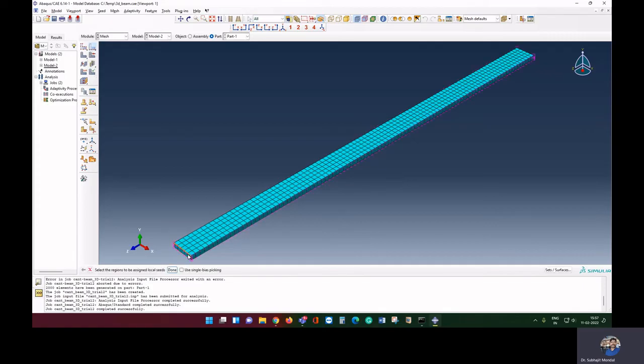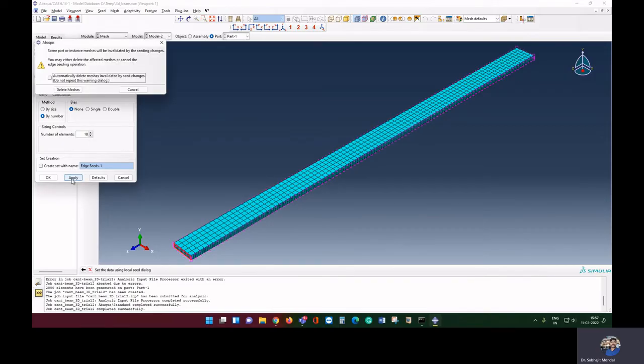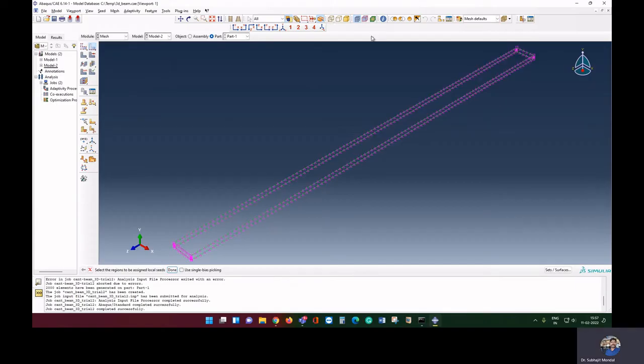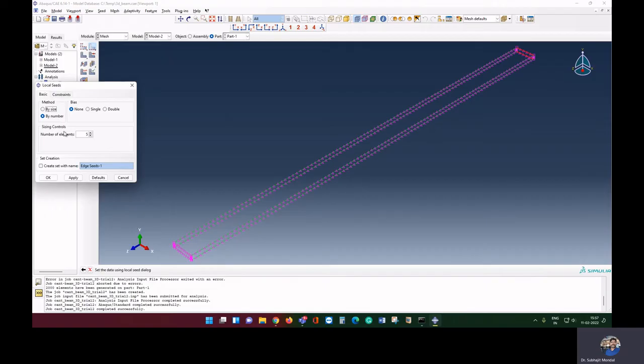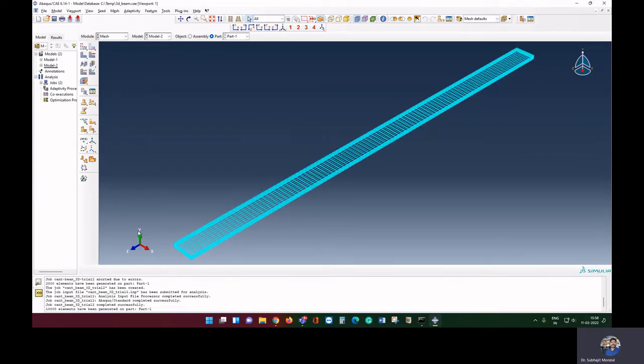So now we'll do one thing. We'll increase the mesh size along this width. Now here my number, I will try to make it as 20. No, sorry, 10. I'll make it as 10. This side also I'll use as 10. Here also I'll use 10. So I will make the number 10. Okay, now if we make it 10, we'll do the meshing and we'll see.